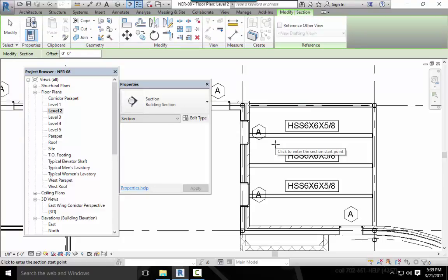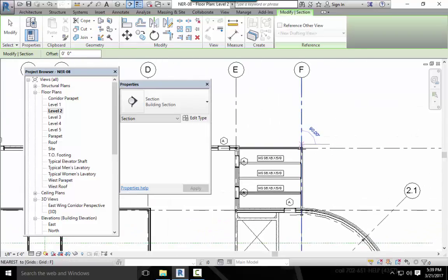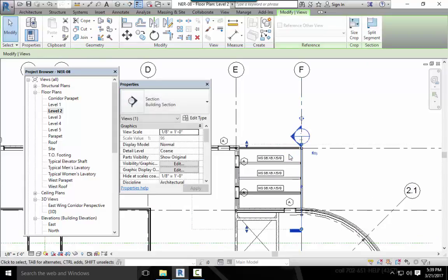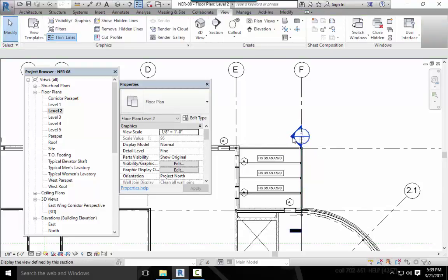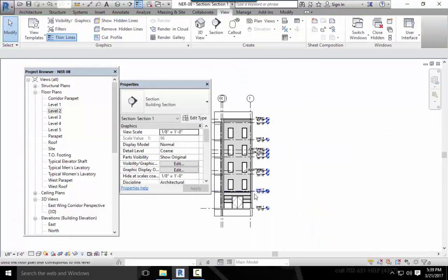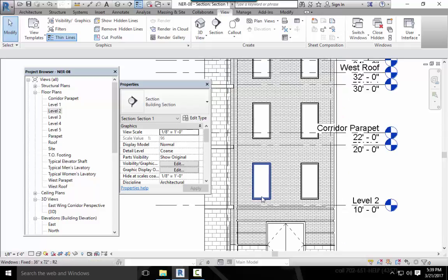Place the section along column F in Figure 8.47. Okay. I'm going to flip this because it's actually showing the section looking in that direction. Open the section. Rename the section Framing at North Canopy Elevation. Oh, no, just Framing at North Canopy.